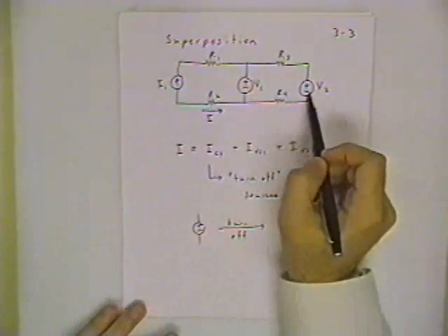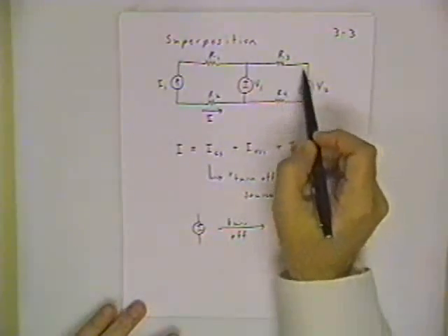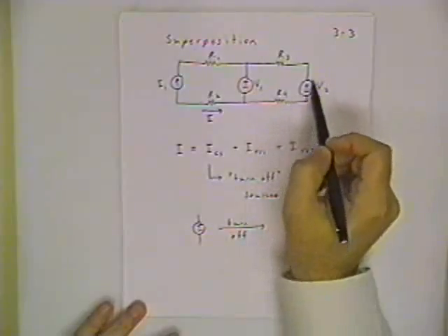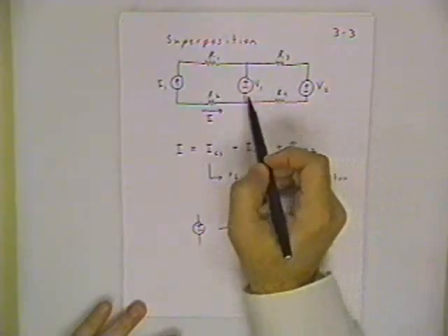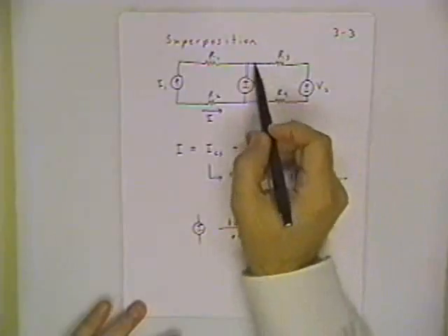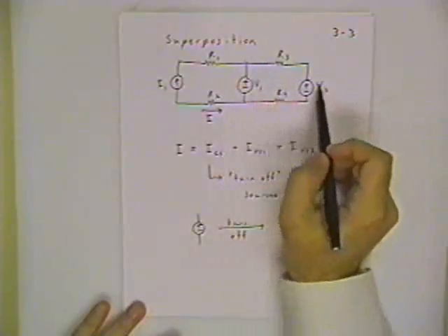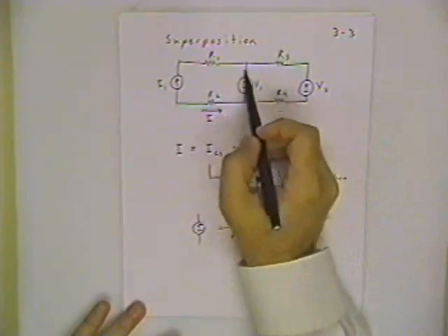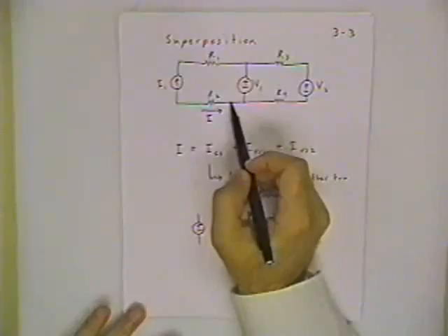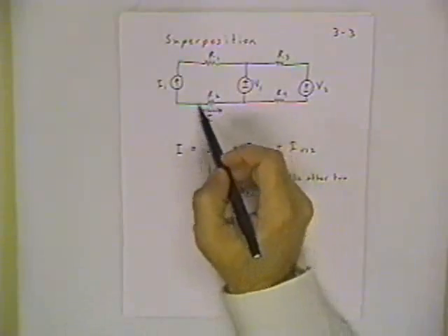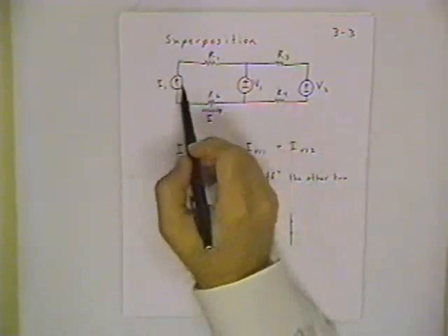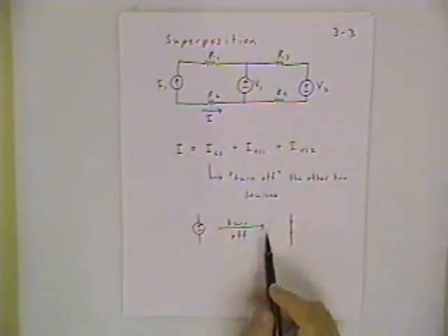And you see what would happen is if you make this a short circuit, that puts these two resistors in series, so you would have a simplification there. These two resistors in series would be in parallel with a 0 ohm resistance if I short out this voltage source. So that whole network boils down to a short circuit, and you can calculate the current I now is just equal to the opposite of the source current I.